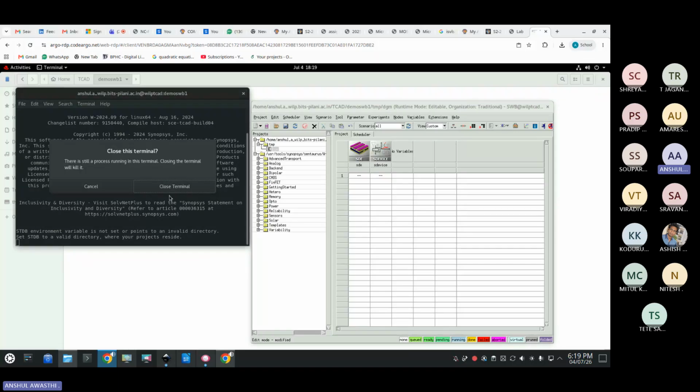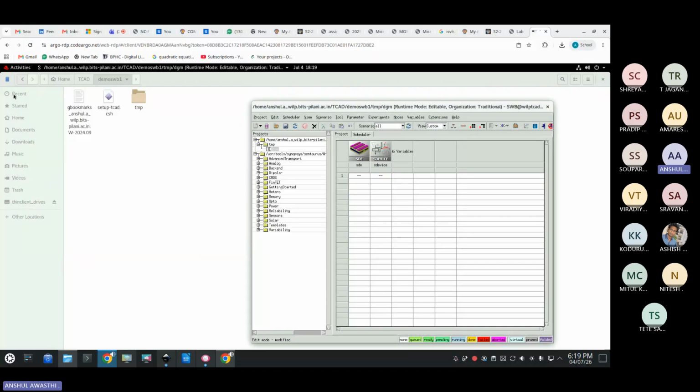What next will we do? We want to add the SCM file. The input to SDE will be either an SCM file or a GRL file. In the first part, I'll show you how to use the SCM file. I have an SCM file with me, and I'll copy that.